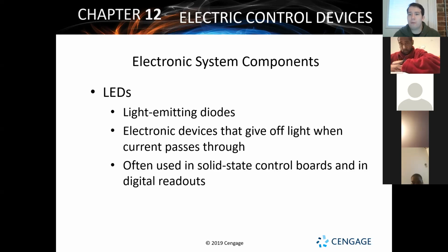So typically for indoor units, for gas furnaces especially, a gas furnace is going to have a safety on it. When you take off the panel to get access to the control board, you're entering an area that has high voltage and low voltage. To protect Joe Schmo, who thinks, I watched a YouTube video and I know how to fix my furnace, from hurting himself, all furnaces are equipped with a switch. As soon as you take that panel off, the switch opens and disconnects power to everything inside there. That includes that LED light, and the LED is going to have an error code.